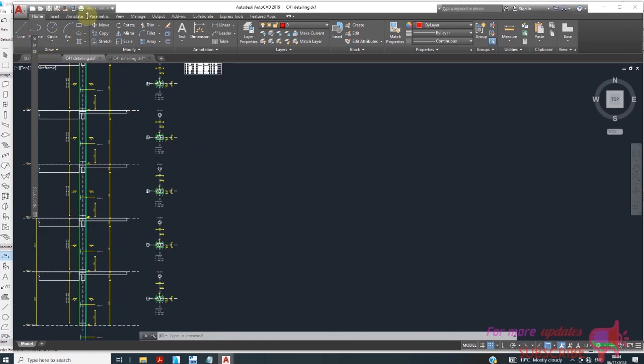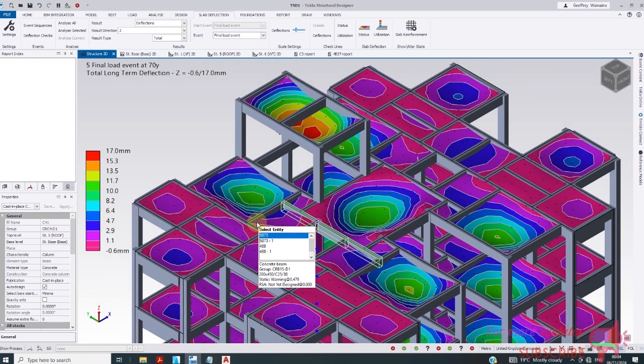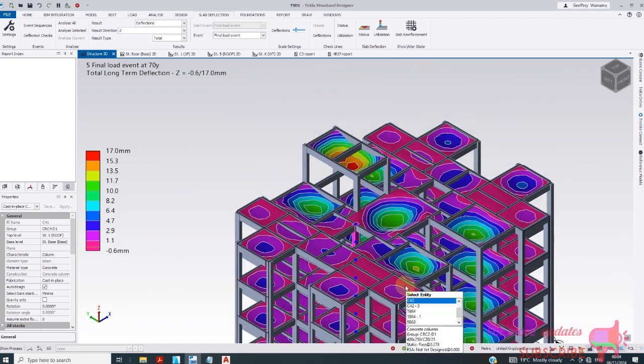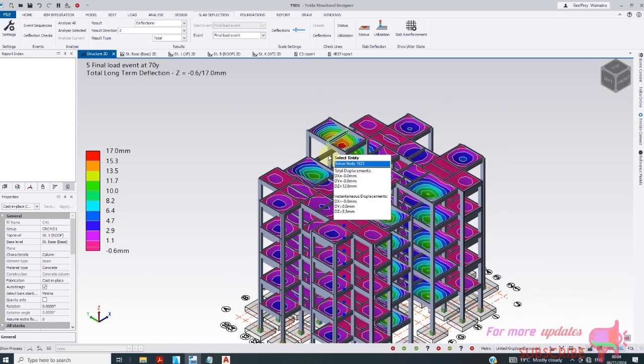So you can go to calculator. The allowable deflection should be not more than, let's say, 4900 divided by 500, because that is the Ly. 9.8, this is the maximum deflection allowed. Therefore, it means that this is failing in deflection. These greens are failing in deflection because the maximum allowed is this color and below. So that's how we do deflection check.